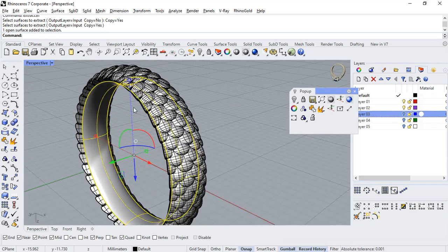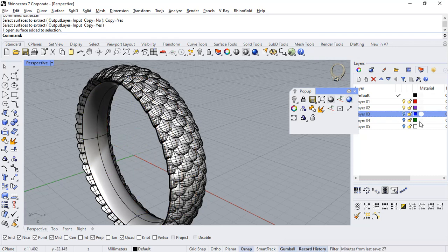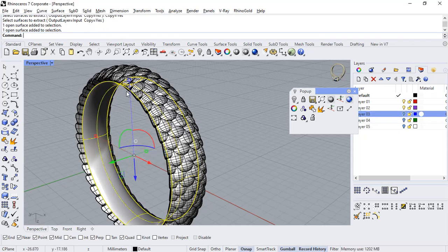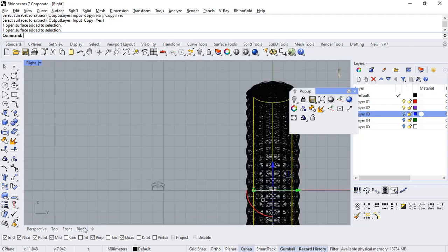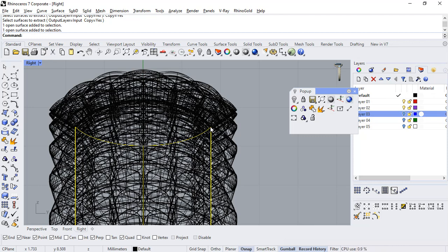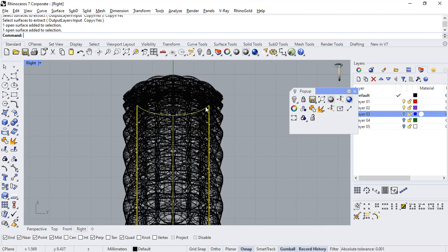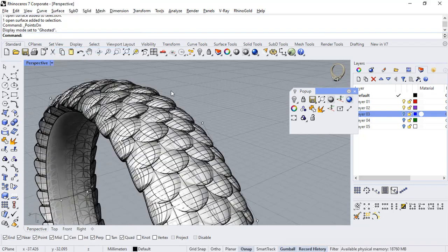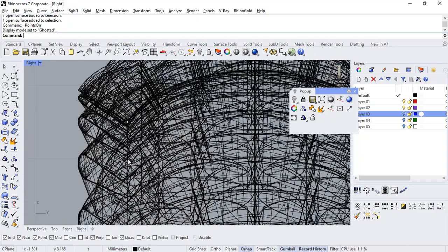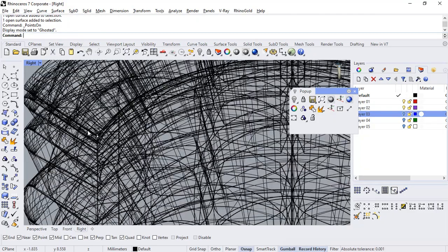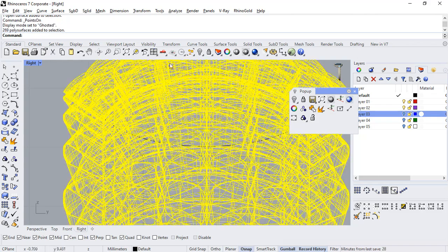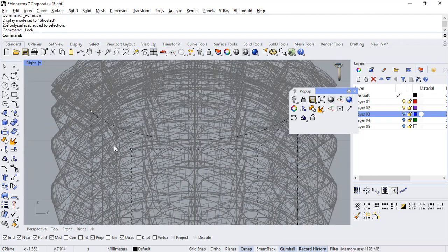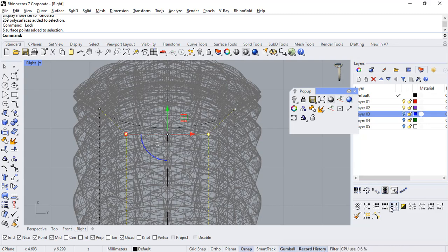Okay, so this is my current existing model. Okay, but let's make it a little bit extendable. So this will extend in this way, but I want to go this way. So let's turn control points on, then make it go straight. Okay, so I can see through. Go to right view. Okay, these are the points. Okay, select this group and lock it, so we can properly see these inside curves. Okay, so this way we can select inside curves and now select UV.